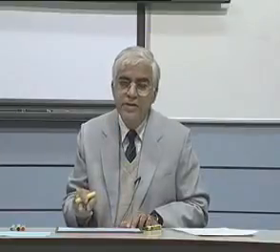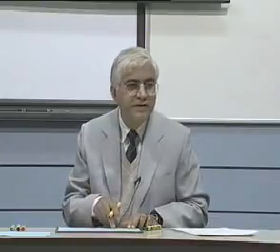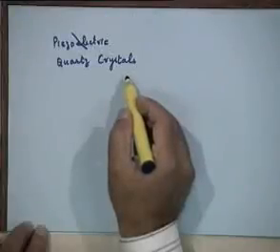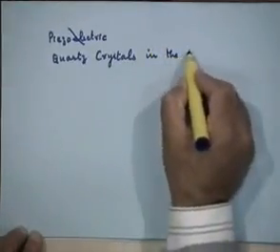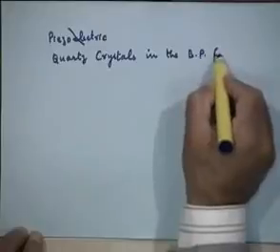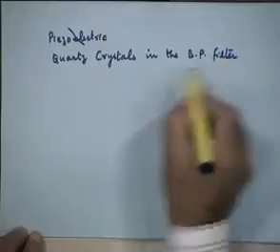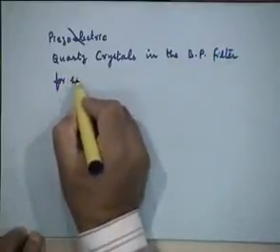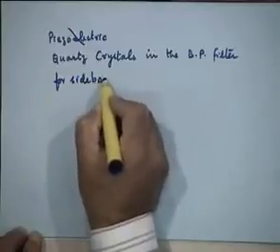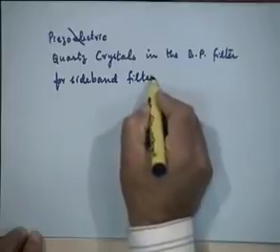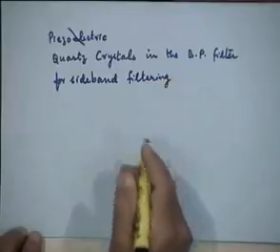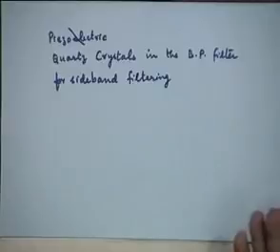So you could get the kind of filters that you want to design for the SSB generation by using quartz crystals. So you will use quartz crystals in the band pass filter for sideband filtering. More about this later if we get the time. At the moment, I just want to mention this fact because I don't want to get into a discussion on how quartz crystals work in this connection.